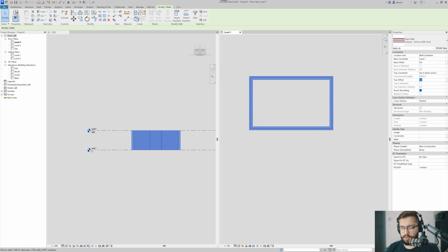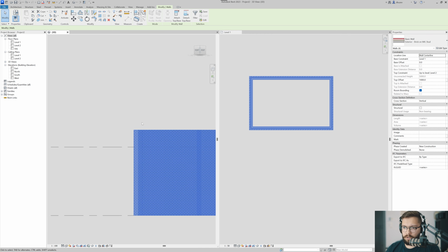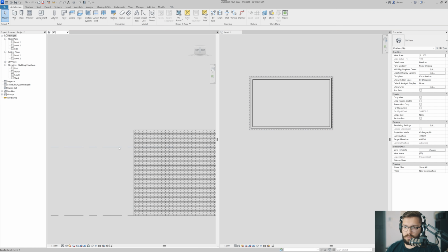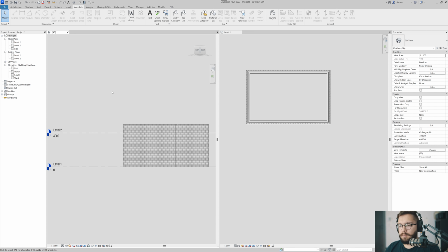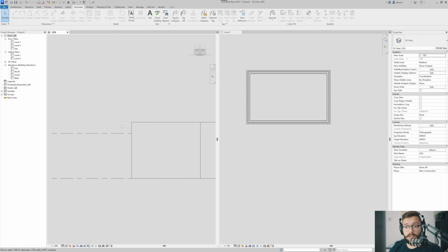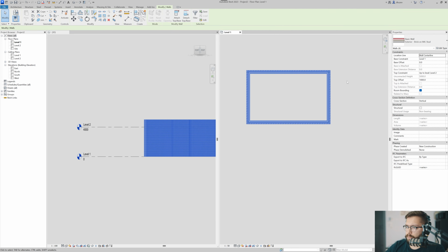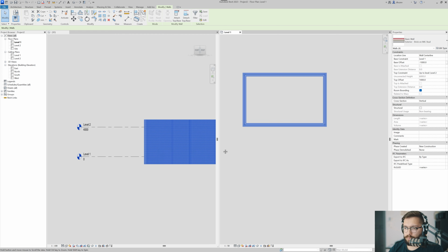So in Revit, if you're a newbie, hi, you can just type 1M and hit enter. So this would automatically set 1000 millimeters. And you would see that here I would have exactly 1 meter of what? Because I'm in 3D, obviously, never mind. But it surpasses it here by a meter. If I select my walls again, you will see that there's this thing called base offset. So it's very similar, exactly the same thing as the top constraint. If I do 1000, you'll see it's going to lift it up. If I do negative 1000, it will bring it down.